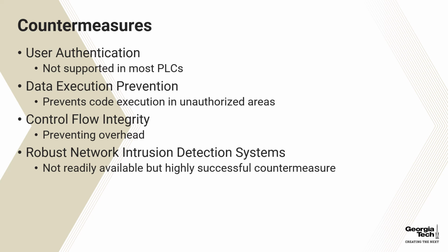Next, we have data execution prevention. This is very effective at protecting against unauthorized zones of execution, and is widely used in desktop and server environments. It is proposed that the memory management unit needed to utilize such protections in those environments could be substituted by a memory protection unit found within available microcontrollers.